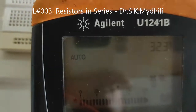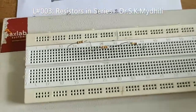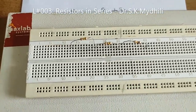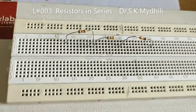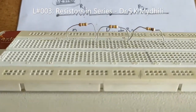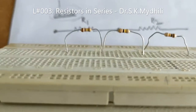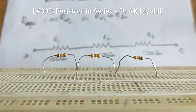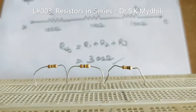So this is how you can check in terms of resistances, and how the connection should be given in the breadboard is also clear. Hope you understood today's topic, how to connect resistances in series, how the same node appears. So you could see here across the node potential where I have connected these 3 points. Okay, so this is how I have obtained a 300 ohm value resistance.